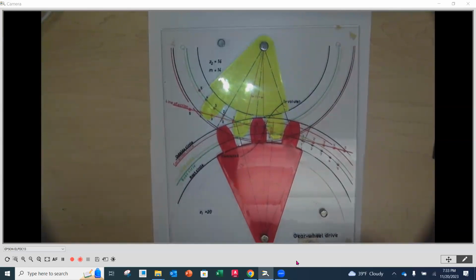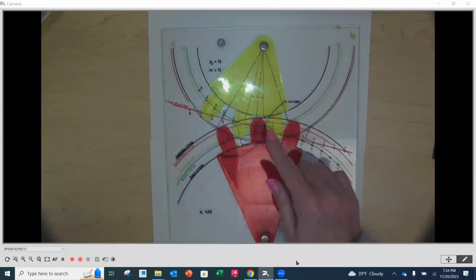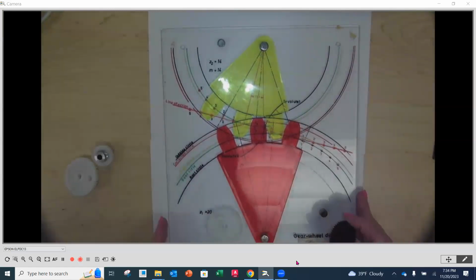We always want to know, for instance, when we lay things out, how much space this is going to take up, all right? But diametral pitch is the size of that tooth. So as that gets bigger and smaller, that's going to change this diameter as well, depending on how many teeth are on there. Now, I also have a couple of gears here, and I'll send these around.